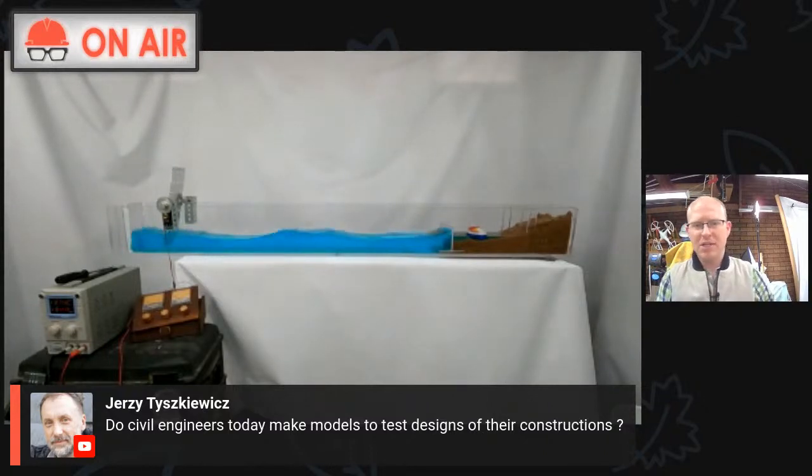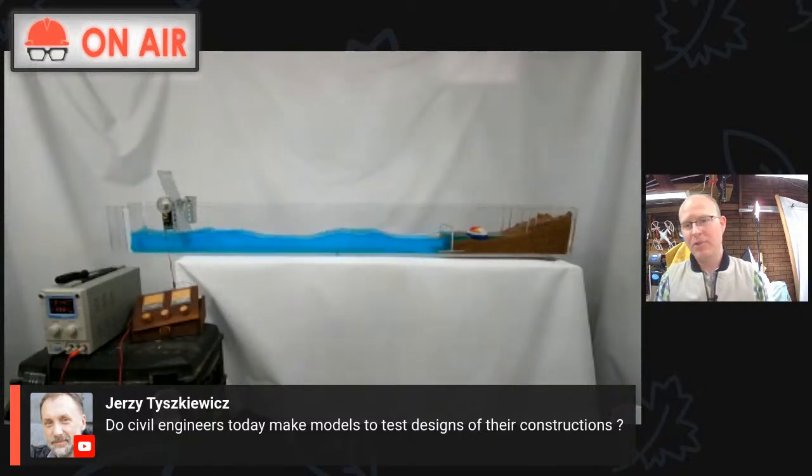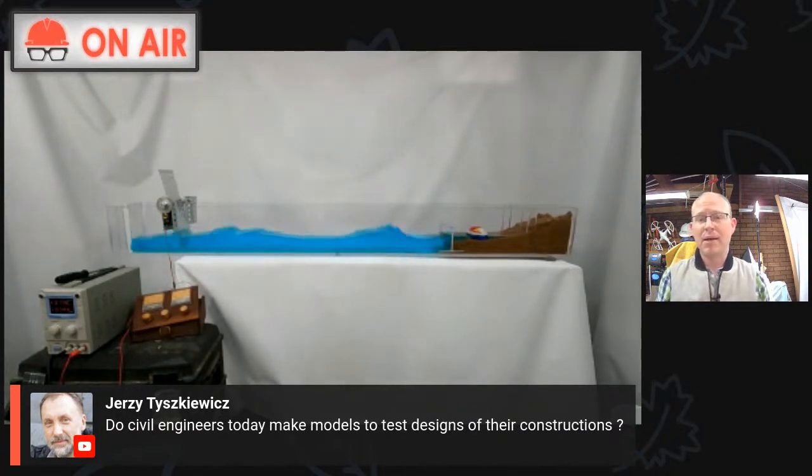Jersey says, do civil engineers today make models to test designs of their constructions? And the answer to that is yes, they do. There are a few different fields of civil engineering where the computer models can only do so much. One of them is hydraulics. For spillways and pump stations and anywhere where you have complex hydraulic phenomena, you can only do so much with a computer model. So yes, we still build scale physical models to characterize hydraulic phenomena.